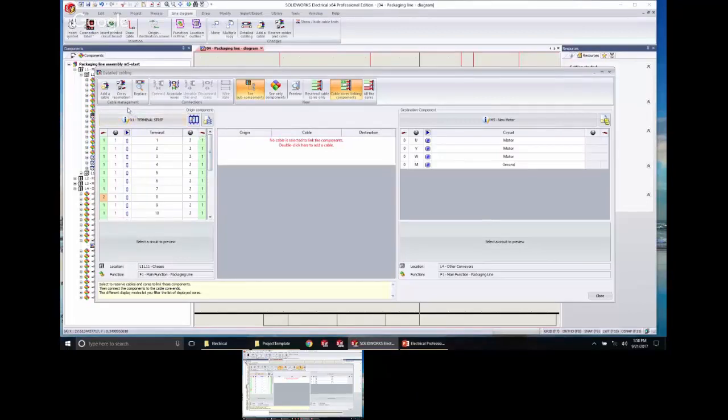Okay. So if I'm creating a brand new one, I can just select add cable here. And as I said, it takes you automatically into the SQL database. You go in, you find the type of cable you want. If no cable exists, you want to create a new one, no problem. What you have to do though, there's no new button here. What I suggest is find a cable that's close to the one you want to create, and then just right click and select add.